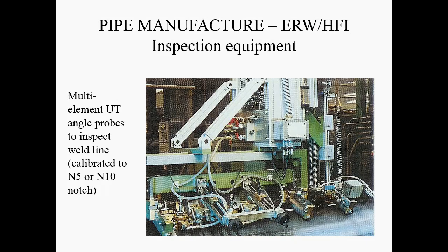When you're treating the weld, does it mean the temperature will not go through? Yeah, the heat is just focused on that weld line. So if the weld is lined like this, you have an inductor that's lined like this, and it just heats up the weld region. And then you have to line that up along the process direction. So if you do it correctly, the rest of the pipe stays cold. It doesn't actually stay cold, but the heat on the weld takes you into this high temperature 900 degrees C range, but the rest of the material is only a few hundred degrees C.